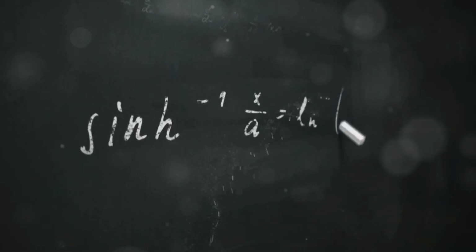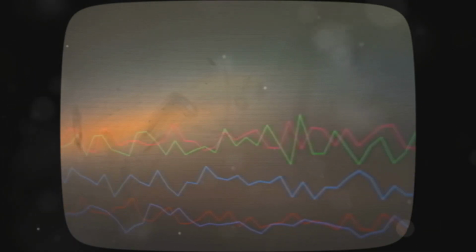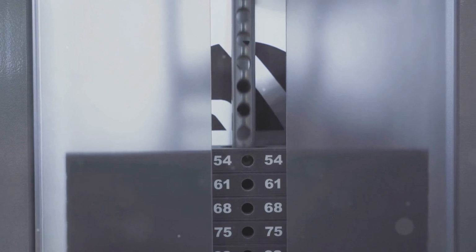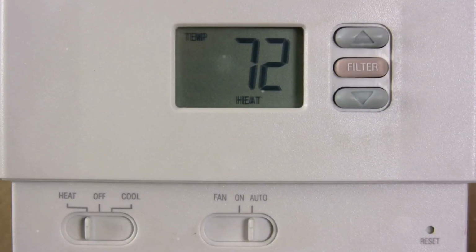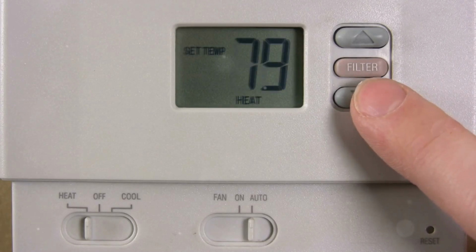The LQR cost function typically includes state deviations and control effort. State deviations are how far the system's states are from desired values, while control effort reflects the resources required. By assigning weights to these components, we can prioritize aspects of the system's performance. For instance, if minimizing energy consumption is crucial, we might assign a higher weight to control effort.